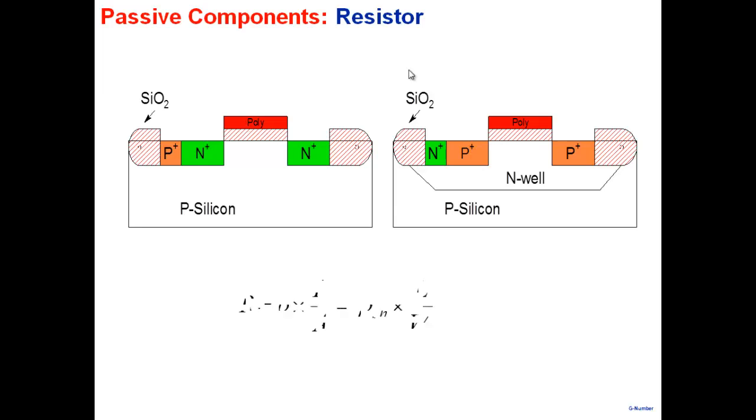So when you make a resistor, all of you know this, R equals rho L by A. And normally when we talk about resistors, we don't talk in terms of resistivity. What we do is take the width and the thickness out of the area. So the resistivity divided by thickness is what we call sheet resistance.